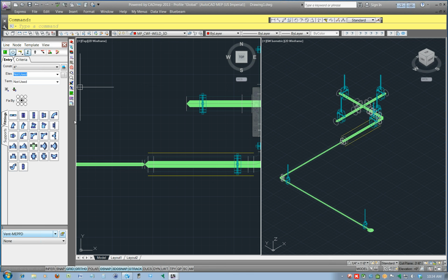See, on mine I have this whole extra section of information here, where it allows me to select insulation on and the size of the insulation, and then when I fill it in and I want my hangers on it, my hangers are oversized for the insulation. I mean, that's got to be in there somewhere. It's probably just turned off. I couldn't imagine that they'd take that out. So in order to add insulation to design line, you're missing something there? Yeah, I'm missing a tool here.